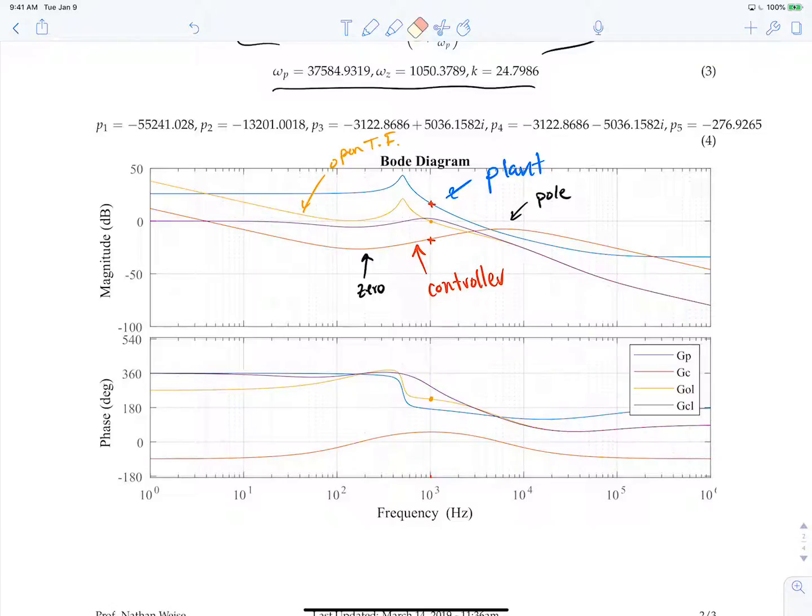You can also relax the constraint on the K-factor approach, so you don't have to put both zeros and both poles at the same location. That's what the K-factor approach does here, so you'd have a double pole, double zero, but you don't have to do that. You could manually start placing them, or you could look at lowering the frequency using the K-factor or increasing the frequency and see if you get better responses and better loop shaping of your open loop transfer function.